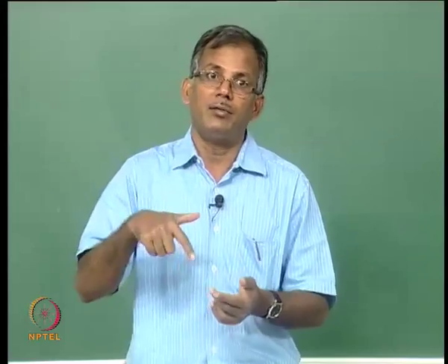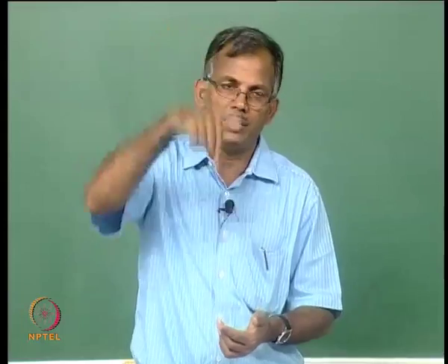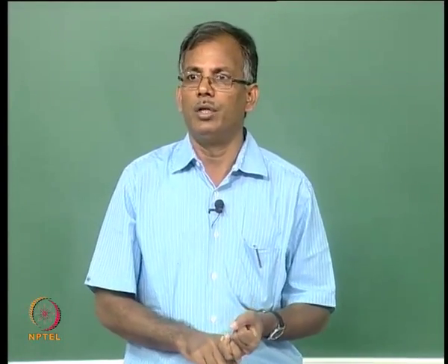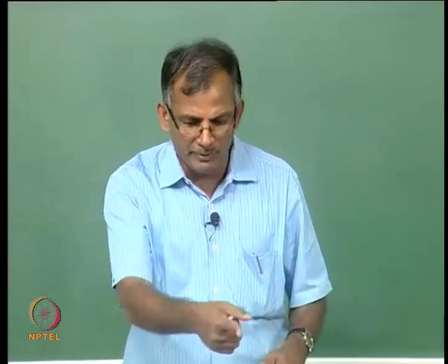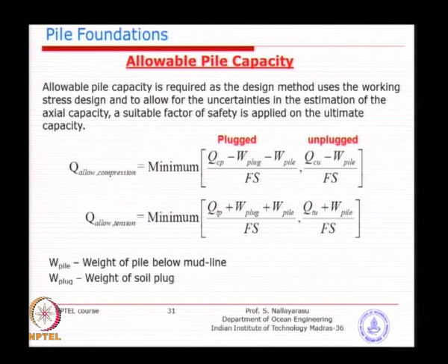So, vice versa, when you are applying a load to the pile above the seabed, say a compression load, the pile weight plus the soil weight must be added to the load itself, because it is part of the system. So, that is where we need to make sure we use this information. In a plugged case, you will remove the pile weight and the soil weight from the capacity divided by the factor of safety, because it is part of the load, whereas for the unplugged case, that means the soil is supported by soil itself, because this soil is not becoming part of the pile, very similar to a solid pile.